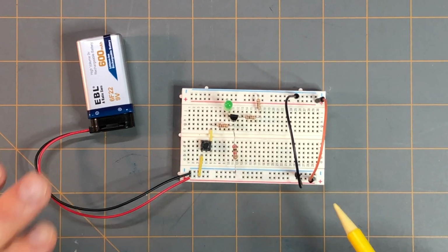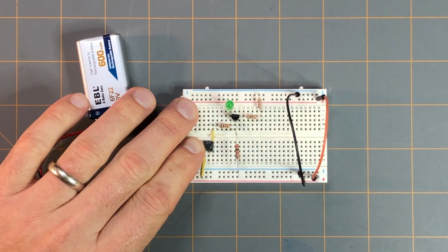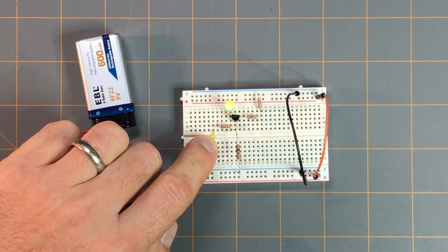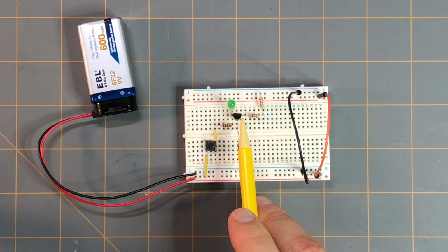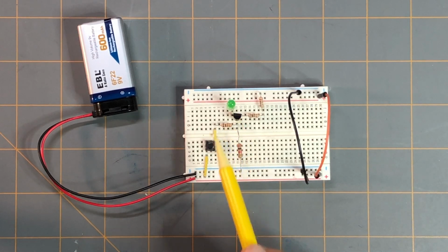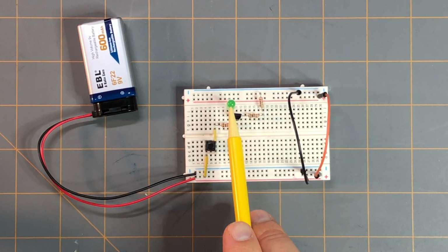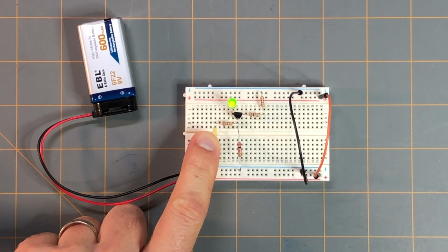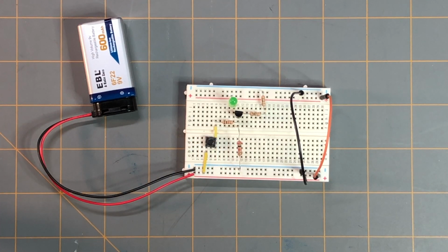So again, this was for the switch application example in the blog post. And if I were to press the button here, we could see that the green LED lights up. And this is all controlled thanks to this N-channel enhancement mode MOSFET. And again, enhancement mode means that it's normally off. So as you can see here, if I'm not pressing the button, the LED is currently off and nothing's happening. If I press the button, the LED comes on. And all that is explained in that blog post that I mentioned.